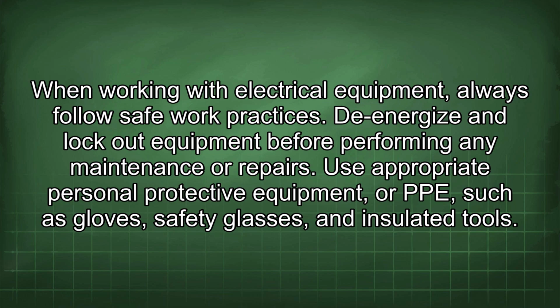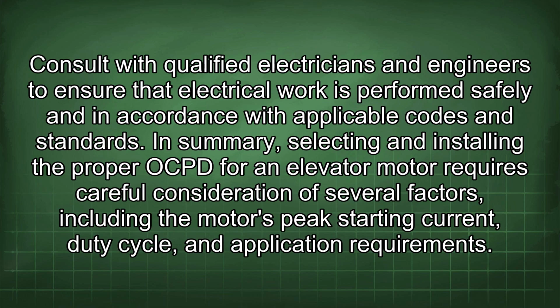De-energize and lock out equipment before performing any maintenance or repairs. Use appropriate personal protective equipment, or PPE, such as gloves, safety glasses, and insulated tools. Consult with qualified electricians and engineers to ensure that electrical work is performed safely and in accordance with applicable codes and standards.